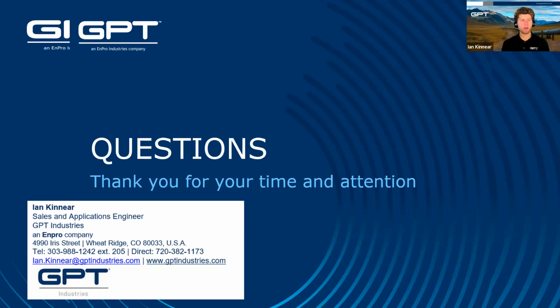Yeah, and that's a great question. It's something that we've seen more and more frequently, this internal current transfer, and it's usually due to the media being conductive. So you're losing isolation right through that media. We've had a lot of success recently using our Evolution gasket, and the reason is that it has an ID seal that you can protrude. So the first thing is making sure your isolation gasket ID matches the pipe bore so that there's not a gap between the flanges where media can build up and this current transfer can happen.